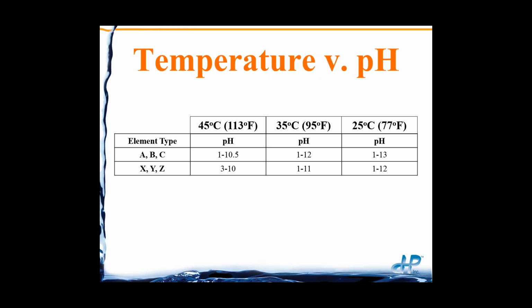Well, that's on a specification sheet. That's not what you're supposed to do at the same time. You don't go to the highest temperature and the highest pH. That's quite aggressive. And chemical cleaning does take life off the membrane. The more aggressive the cleaning, the more life you lose.